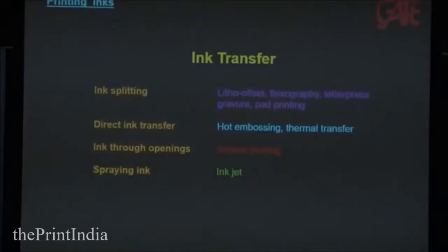Direct ink transfer in hot embossing or thermal transfer. Okay, there are thermal transfer where the ribbon gives impression. The direct ink transfer, ink through the opening, that is in screen printing, and spraying the ink, that is in inkjet. Okay, so these are the different principles of ink transfer. So in ink transfer, how the ink is transferred and whether it's a consistent transfer or not every time, that affects again ink deposition and ultimately color.